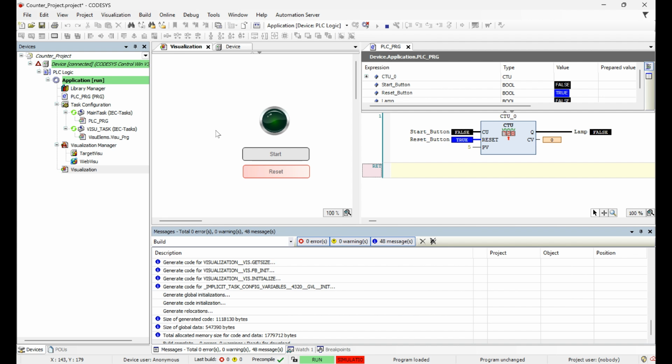You can set it to 10 or 100, and when you add this to more simulations with different IOs, you can have the counter count objects, say 5, 8, 10 or 20, that have gone past a sensor or vision sensor, and then the lamp turns on to show that 5 or 10 objects have passed through the vision sensors on the conveyor.